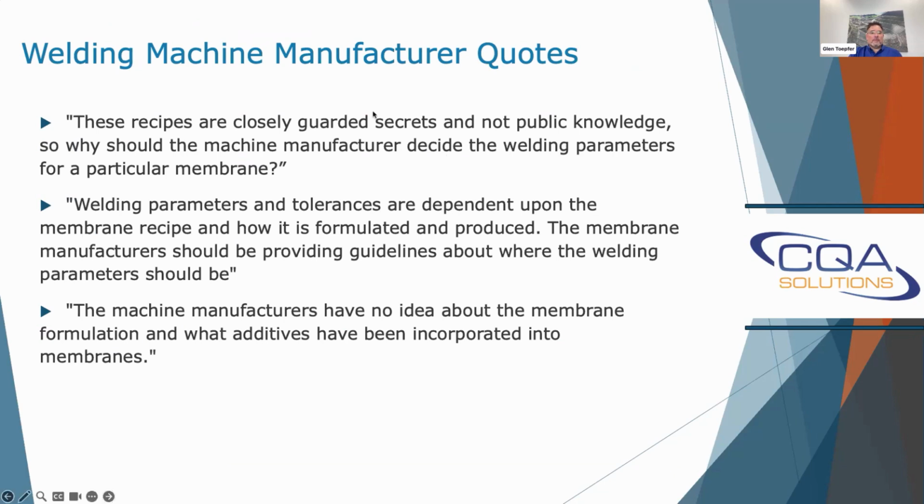Well, that's a good point. Same with the next one: welding parameters and tolerances are dependent upon the geomembrane recipe and how it is formulated and produced. The membrane manufacturer should be providing guidelines about where the welding parameters should be.